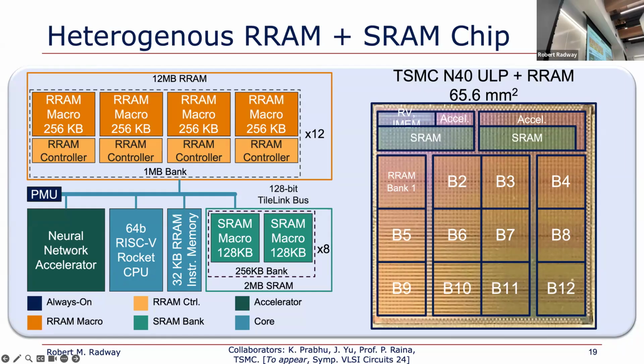So basically 8% of the chip is actual compute. The rest is basically memory. So that's why there's such a focus now on new memory technologies, denser memories, scalable memories, because they dominate the system design. And if you look at today's GPUs, it's very similar. Most of the SMs are actually SRAMs, and then the whole package is mostly DRAM.